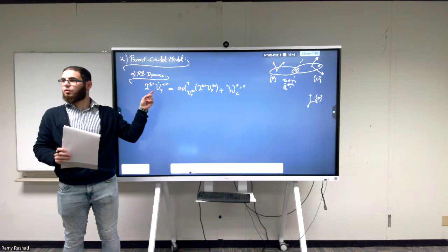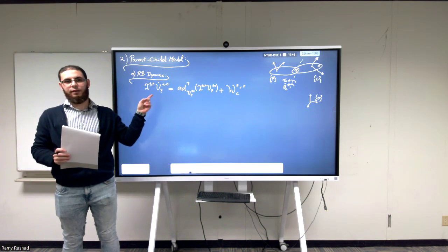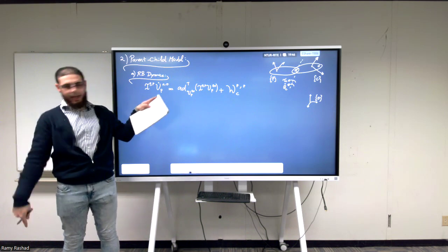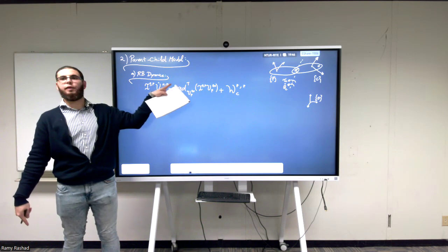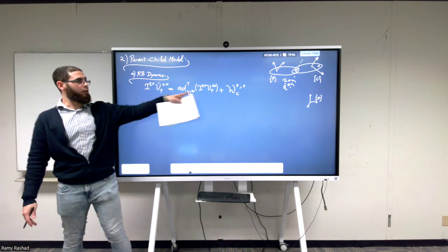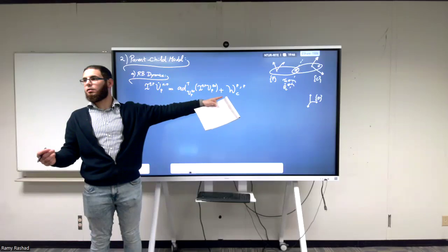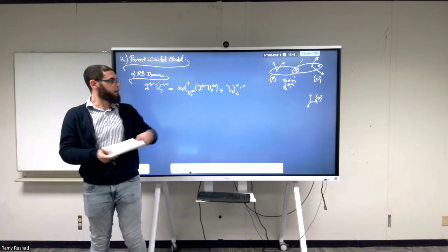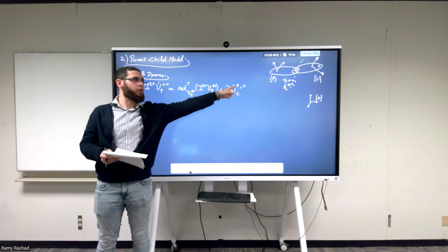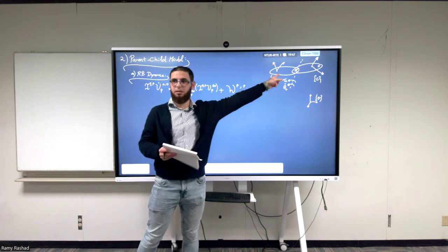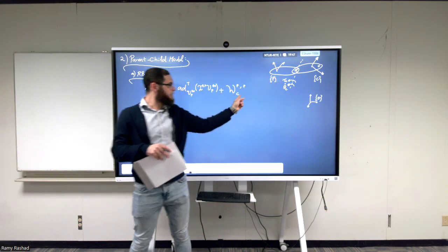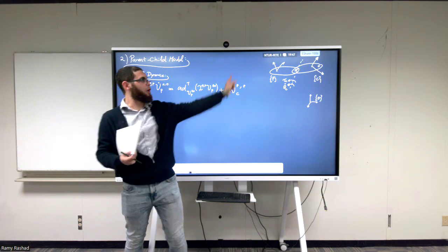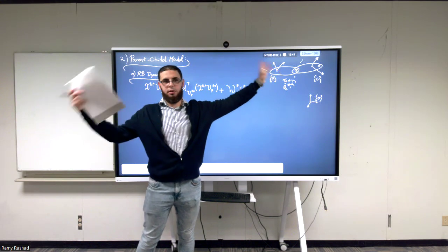When we talk about a twist, how many indices does a twist have? By definition, it has 3 because it's a relative twist between frame A, which is the index down, with respect to frame B expressed in a third frame C. When we talked about the wrench, how many indices did we give it? We give it only 2. We said this is the wrench applied on a body, expressed in some other frame. So here we're talking about the wrench applied on the body P expressed in the P frame. We just denote here that this is the wrench that comes from a source. What kind of source are we talking about? We're talking about the source of frame C or body C, just to be clear.